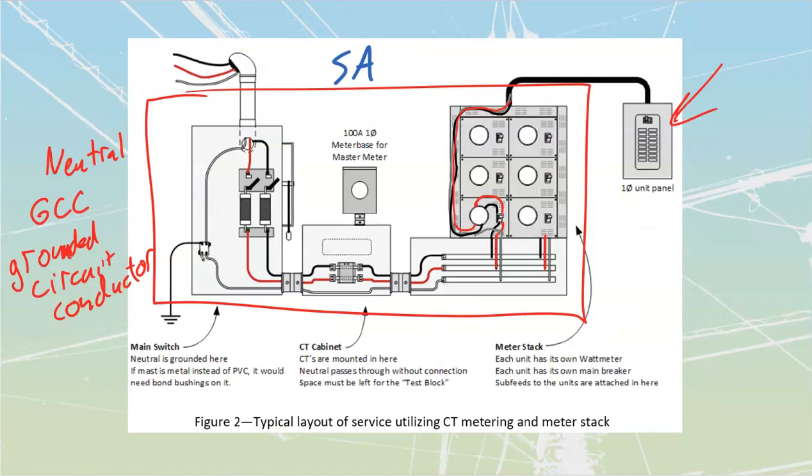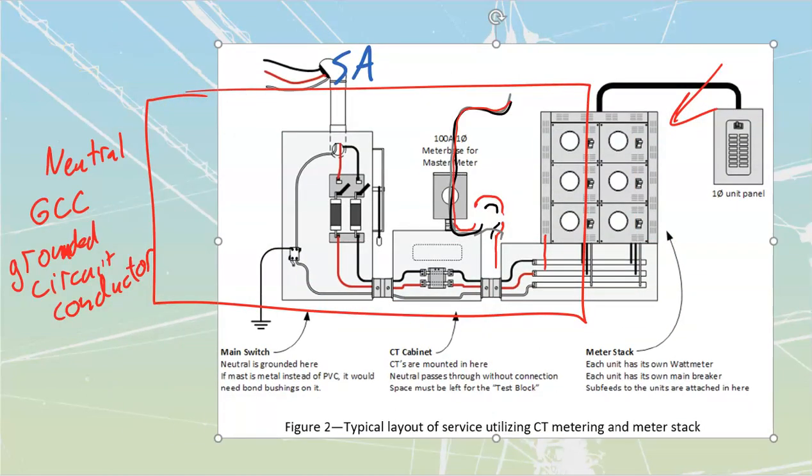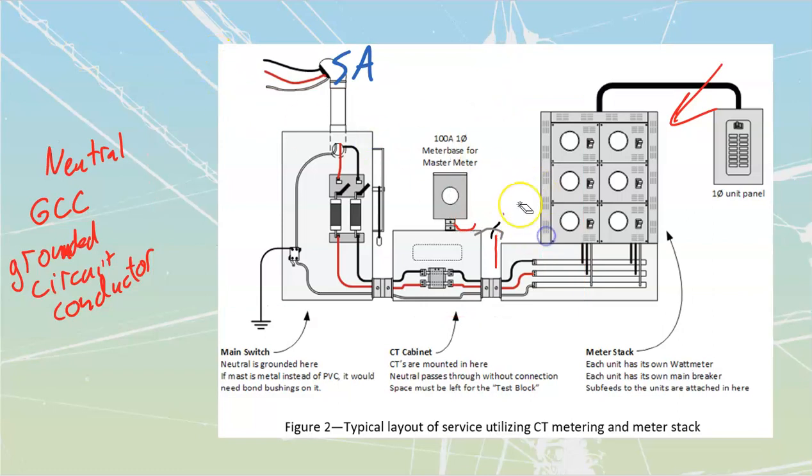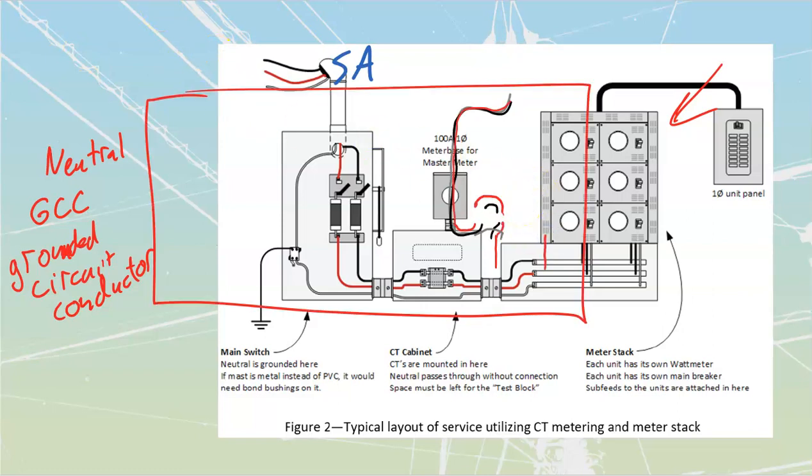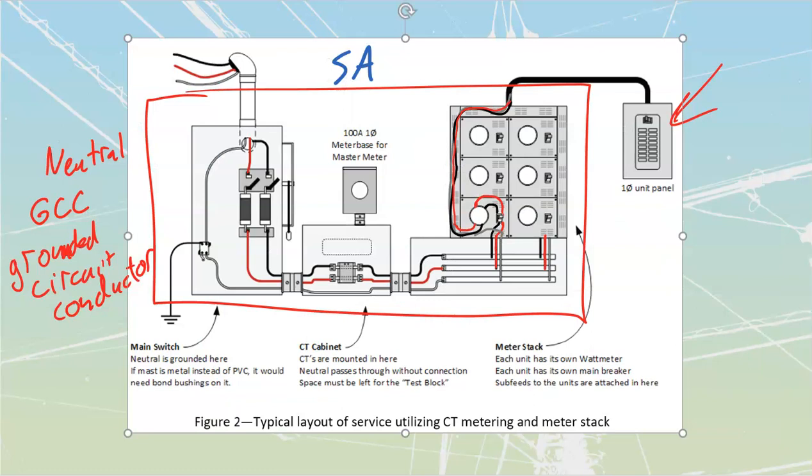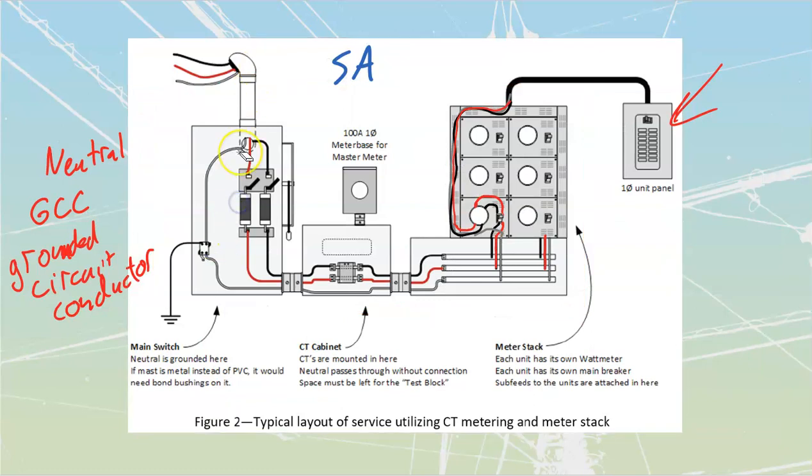We go to this one over here, and what you should note about it is that we now have our main switch ahead of our metering. This is allowable. We expect this to happen.